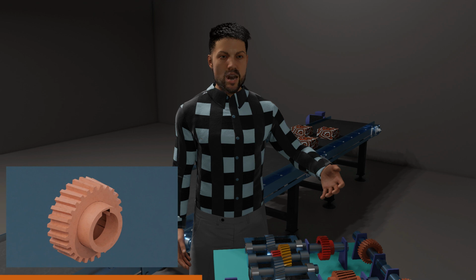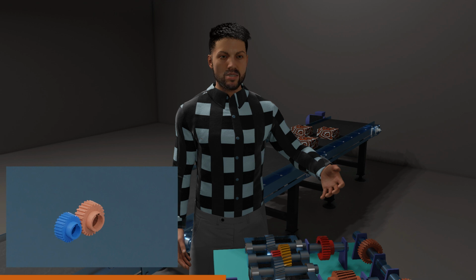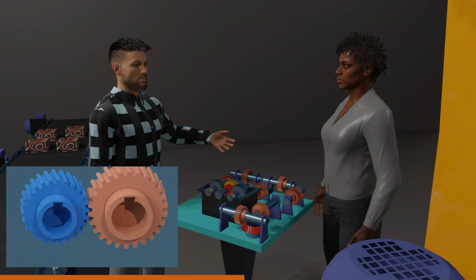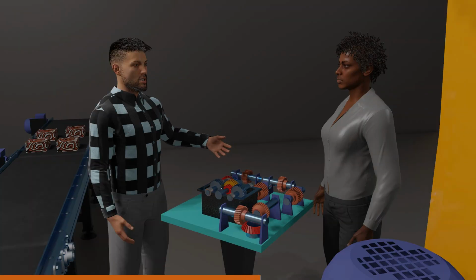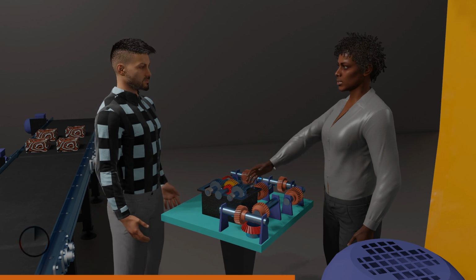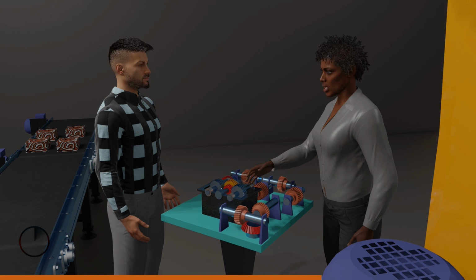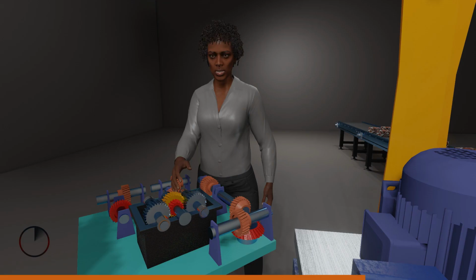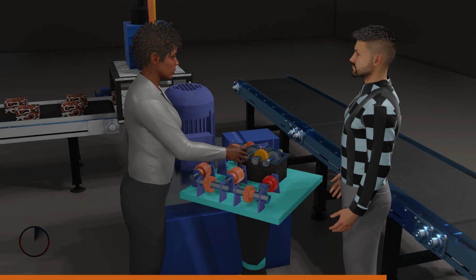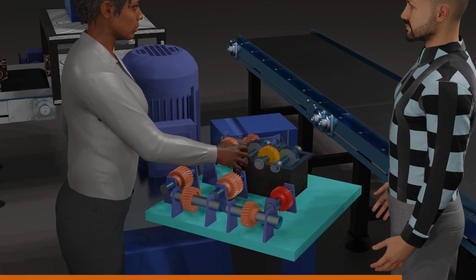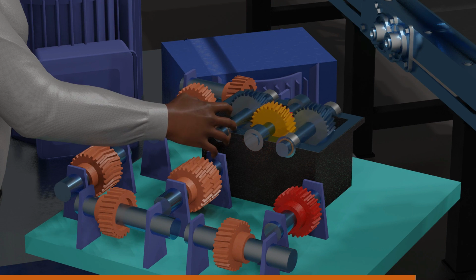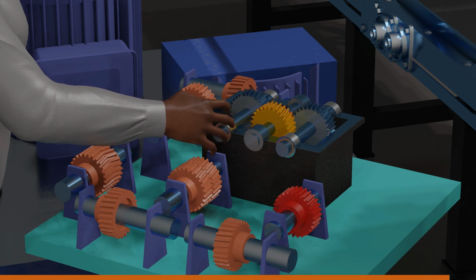Because of the angled teeth design, the teeth allow the gears to mesh smoothly and quietly with less vibration, and higher torque is provided at the output. The teeth design ensures that pressure is gradually distributed along the whole tooth. This gradual distribution is due to the tooth inclination, so helical gear sets run smoother and quieter than other gear sets of different teeth designs, and they are able to carry heavy loads efficiently.